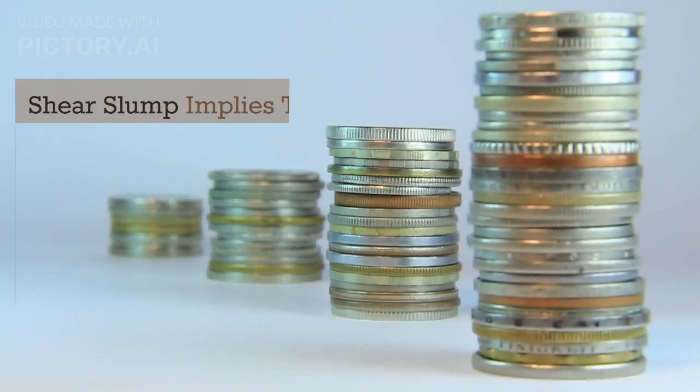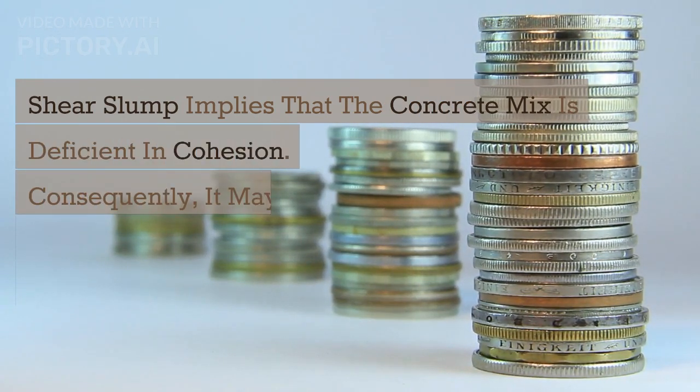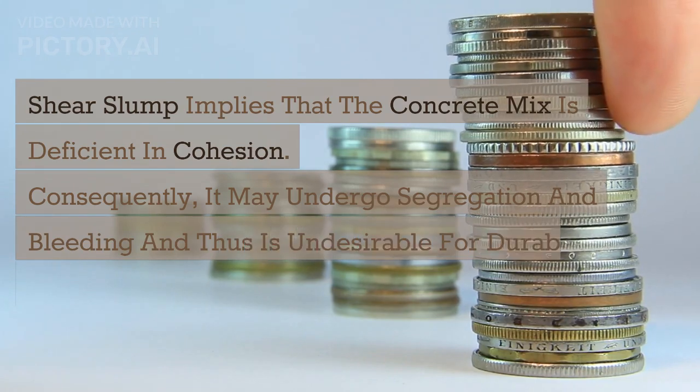Shear slump implies that the concrete mix is deficient in cohesion. Consequently, it may undergo segregation and bleeding and thus is undesirable for durability of concrete.